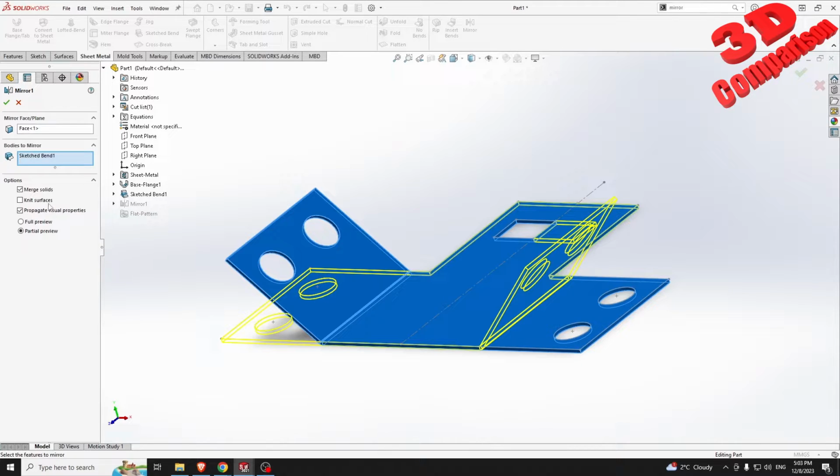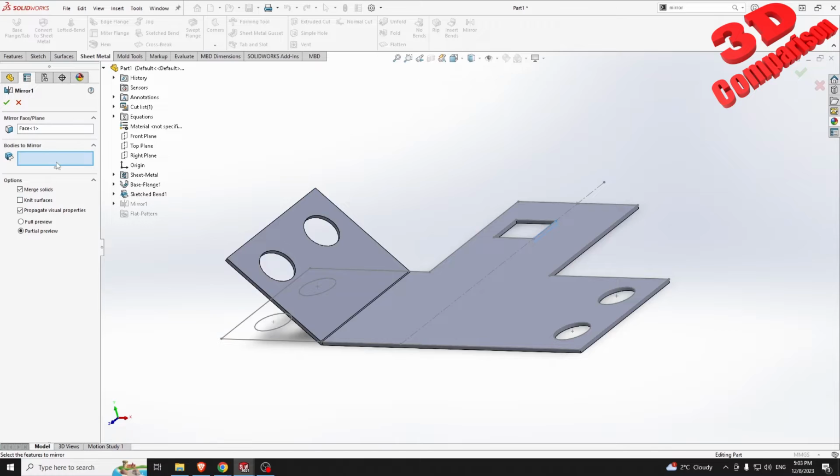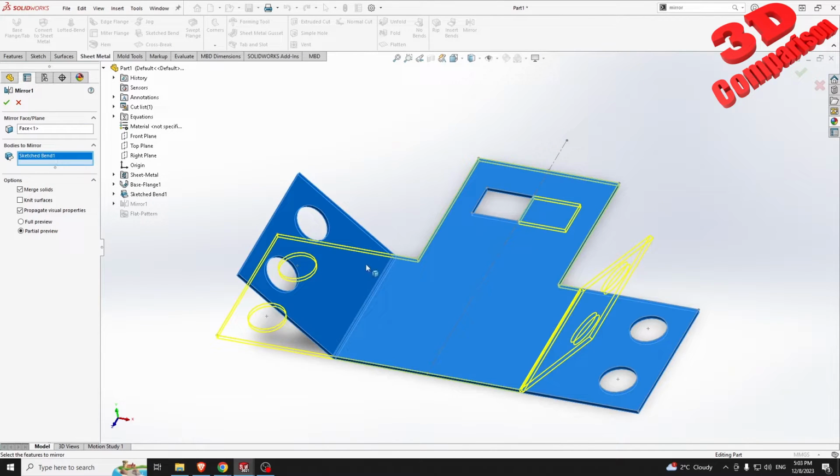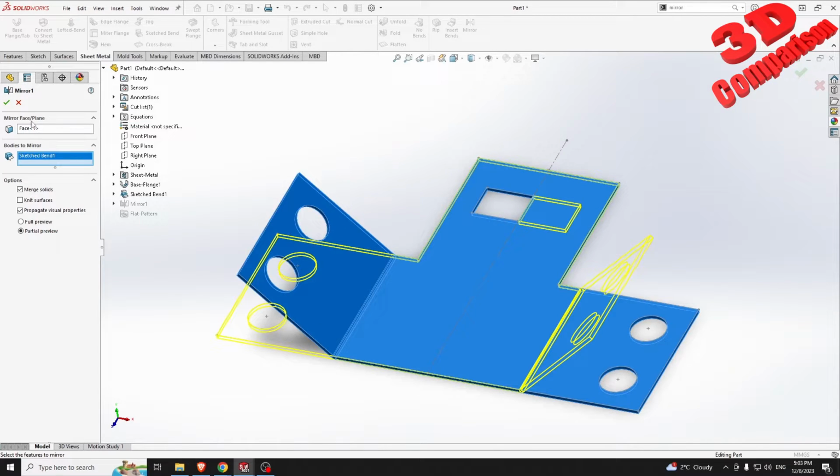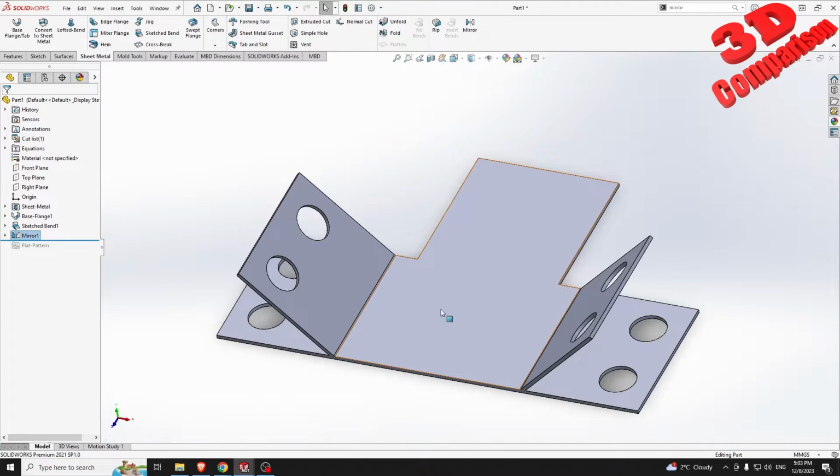Therefore I will go over here and I have the possibility to specify that the sketch body to be mirrored will be this one. It's the same selection, so nothing should change over here, as you can see. And now within this mirror, we can no longer select features. We can only select bodies. And now, as we can see, this will be the output. Therefore, we cannot apply the mirror over here.